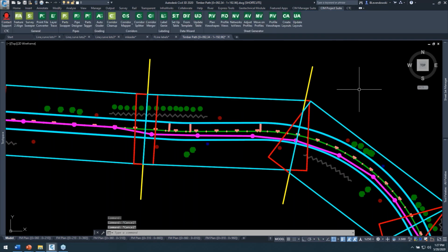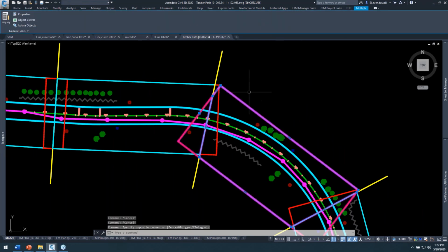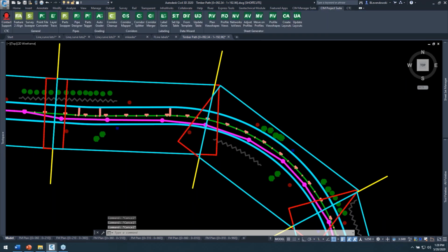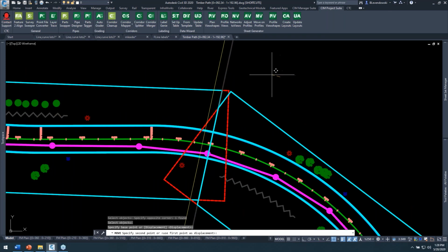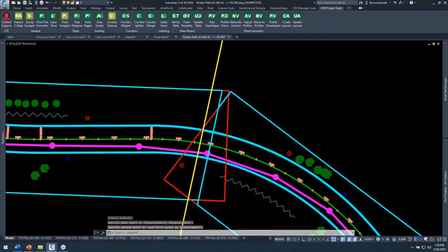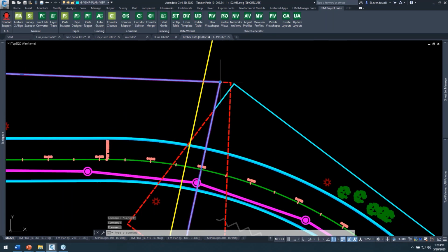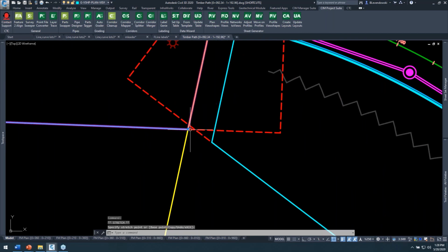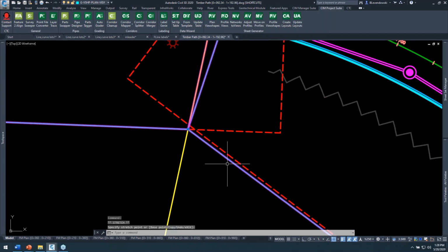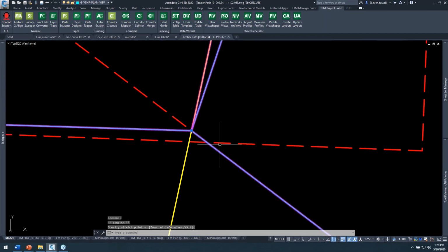And you can angle it. For example, the match line that you were just holding there, it's hovering over top of a structure. And you can very quickly just move that because it's just a polyline. Yep. So we put these in here as just guides, but if you move that around, you could just grab it and adjust your viewport the way you want it to, right? It's just a polyline, so there's no limit to what you can do with it. So if you do that, oops, right there, I think you get the idea.